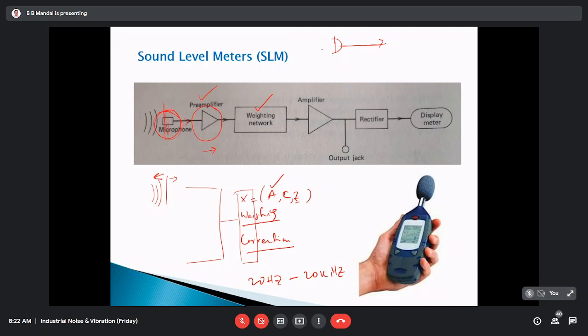So you need to send signals of different frequencies and see the output in the oscilloscope, and from there find out the frequency response curve of the microphone, from say 20 hertz to 20 kilohertz. And when you are giving say 10 dB or 30 dB or 40 dB amplitude, whether it is flat or whether it is like this, what kind of curve it is.